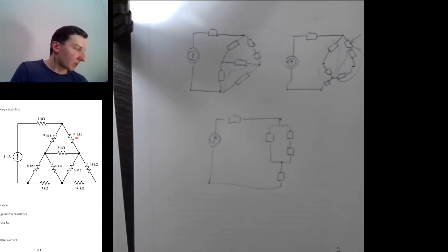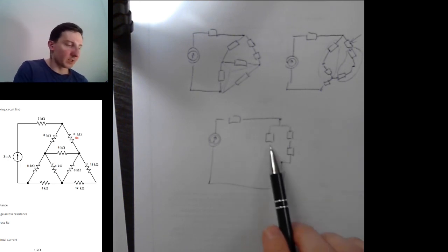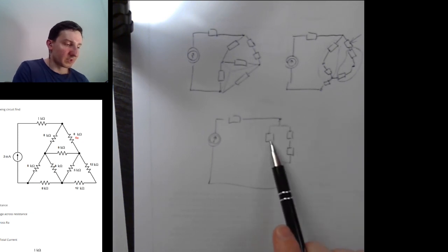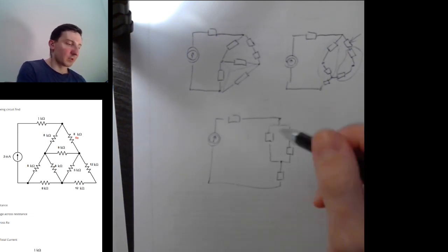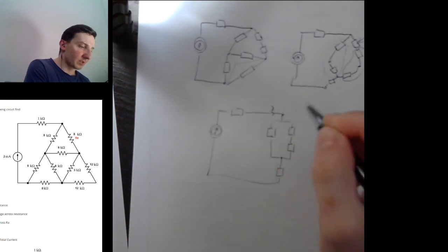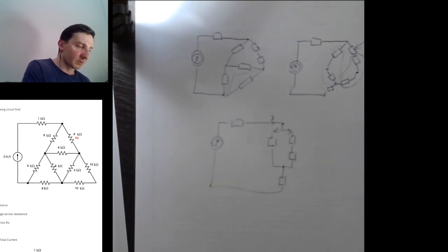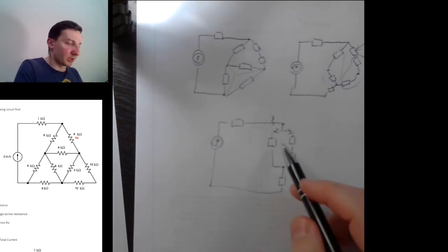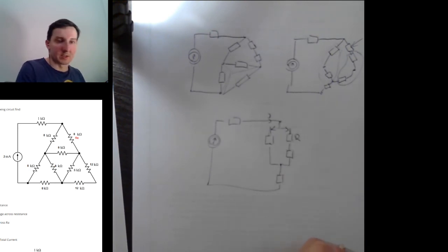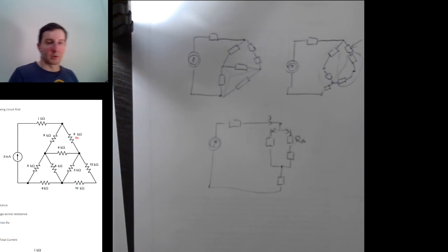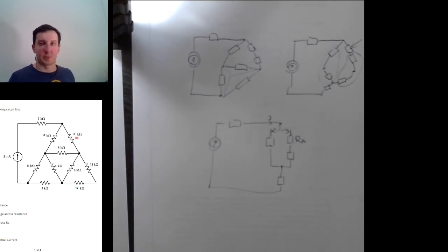We already know what the current is. We can calculate the resistance in this branch and in this branch. So we can easily calculate in what proportions the current flows into each of the branches, and knowing that and knowing this resistance RA, we can calculate the voltage drop. So I hope that this short guidance showed you how to deal with such problems.